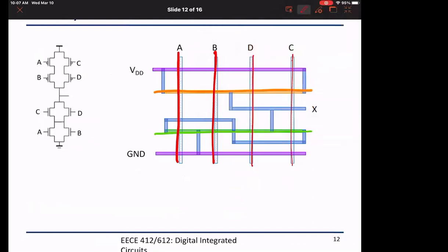Okay, this one took the order. What order did this guy take? He took A, B, D, C. So it's clear he can walk from A to B to D to C. He goes up here and from here takes it and wants to start like this: A, B, D, C. I also have another constraint, which is that the Euler path has to be in the same order to maintain my poly in this clean and clear fashion.